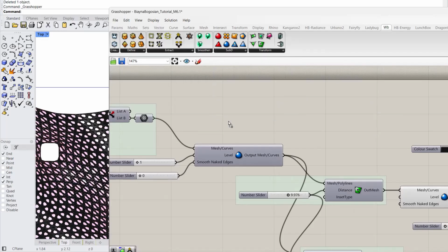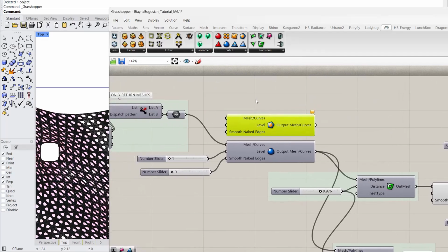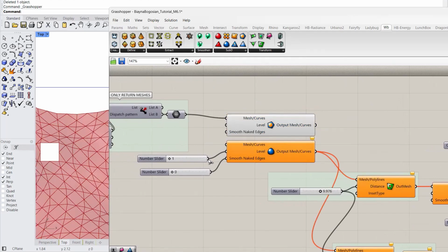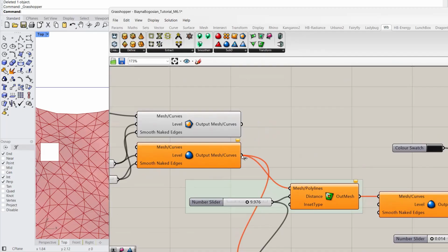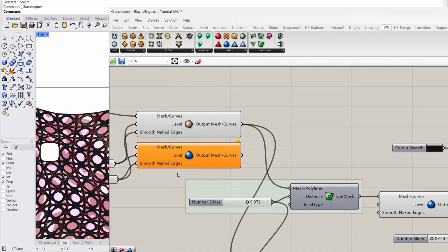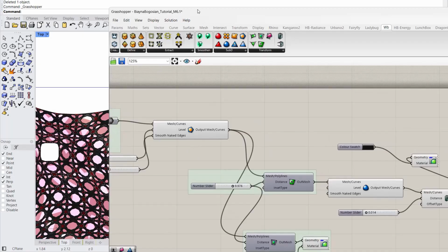So let's use this one. And you'll see that it always has the same input and output. So I am just going to migrate the wire. So I can go directly from here, or that shortcut that we learned earlier. If you hold Control Shift, you can move the wire. And then I can just use the same inputs here. And then again, Control Shift, just move the wire from there to there. And I can just delete this. So that's one way you can swap things.